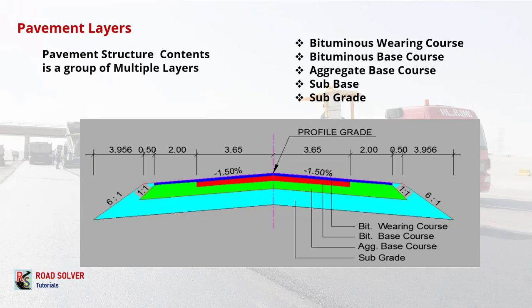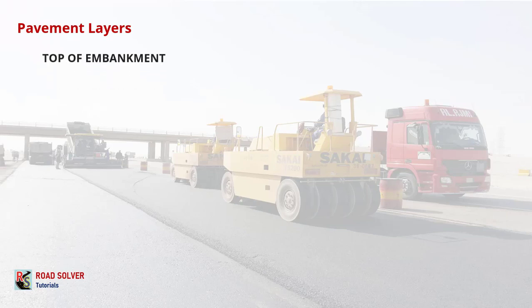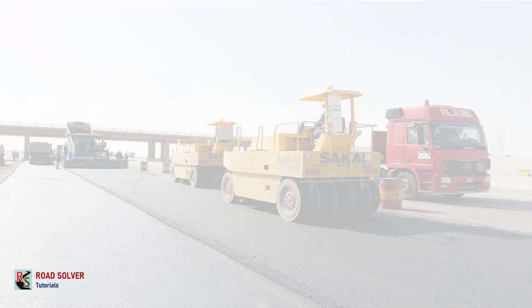For each layer we need the survey levels for the setting out, and we also need the levels for the volume calculation. Also the cut fill section, the top of the embankment layer, is included in the payment layer section in our Road Solver program.